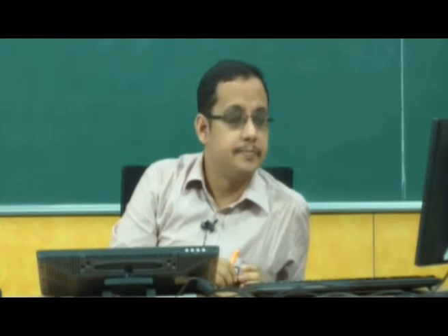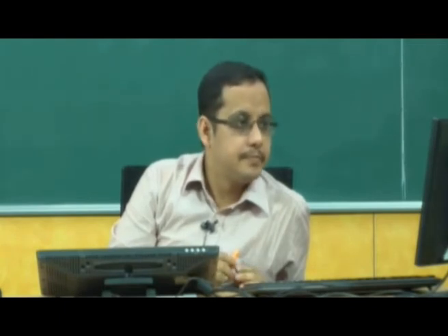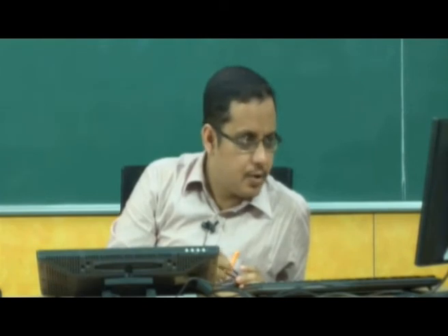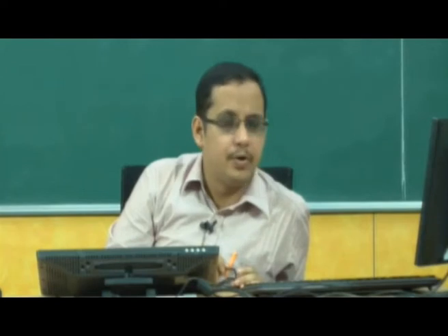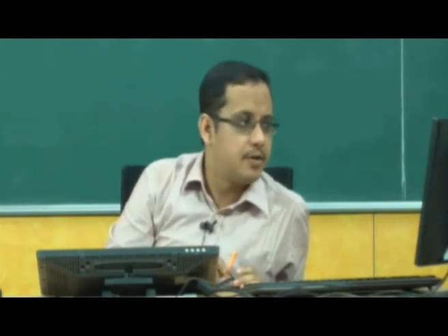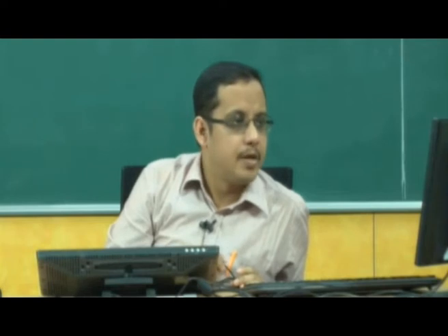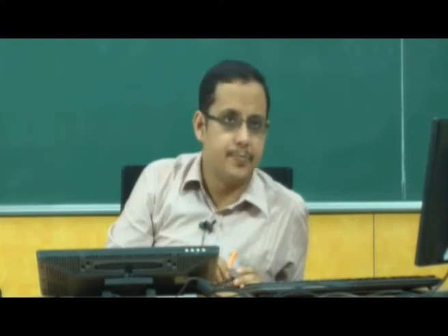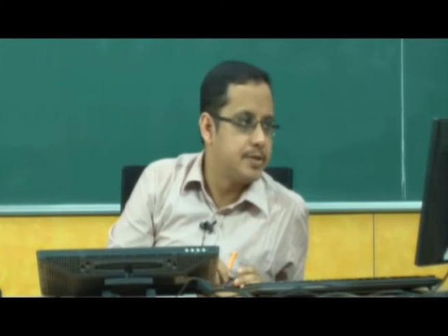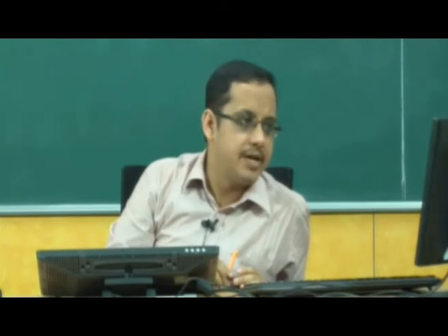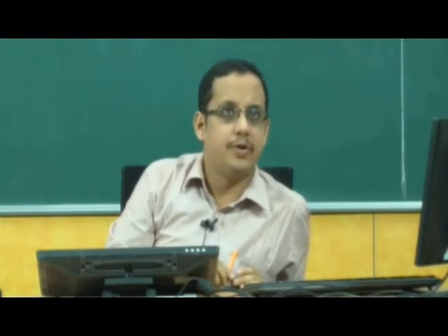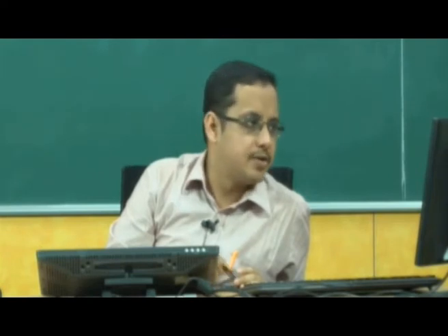Good morning. So we were discussing first order harmonic disturbances. Why didn't we consider second order, third order of omega? In rotary unbalances, you will not get second order and third order. You will only get first order. You will get second order in the case of reciprocating machines. You will not get it in rotating machines. At present we are doing eccentric unbalance, and we are not going to get any higher orders. We are only going to get first order. Thank you, sir.